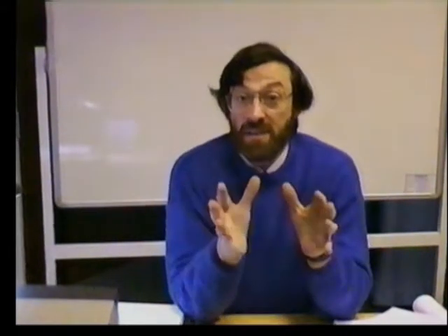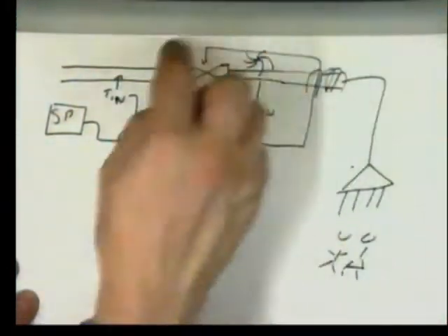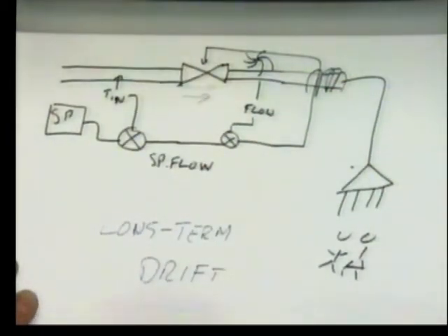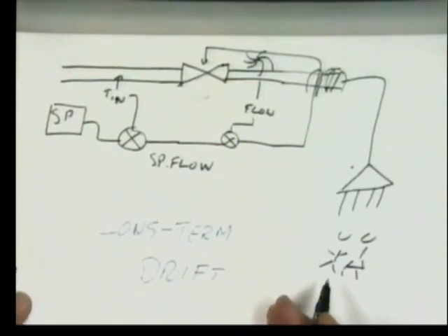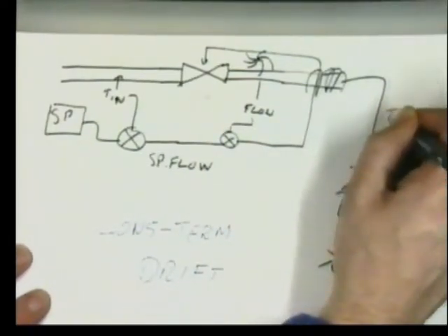Feed-forward control systems can't do that. You've written a model, a mathematical model, an algorithm. If the model changes, your program won't change. It's got to adapt to the new situation. You have to change your model to take account of changes in the system. How can we do that? If you have a system here, this is a fixed model. We have here a program that represents this shower system at the time we manufactured it. But long-term drift will change it. So what we have to do is we have to have another feedback loop. And what we do is we measure the output temperature as well.